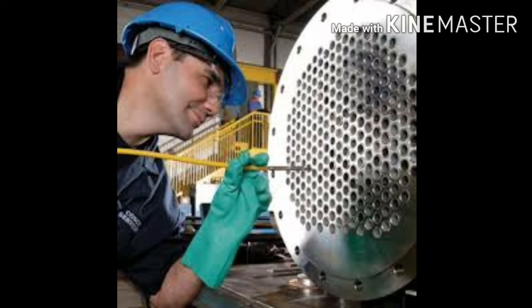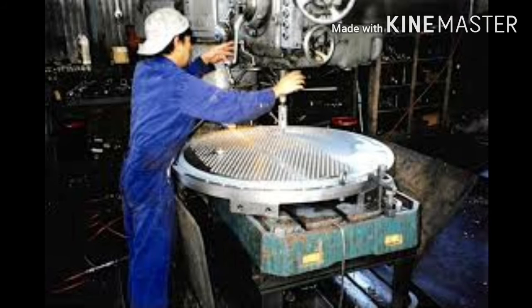Over time, this fouling will compound, which dramatically changes the flow rates of fluid through the exchangers and causes the loss of efficiency, the clog that I said a while ago, and increases the risk of unsafe operation. Moreover, deposits of fouling can cause hot spots and corrosion conditions that lead to premature equipment failure, which is not cost effective.